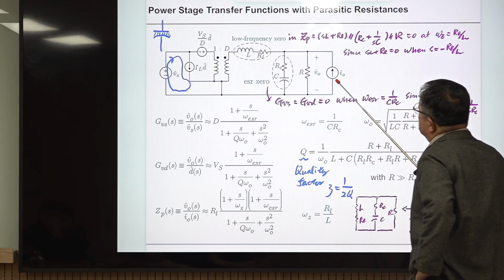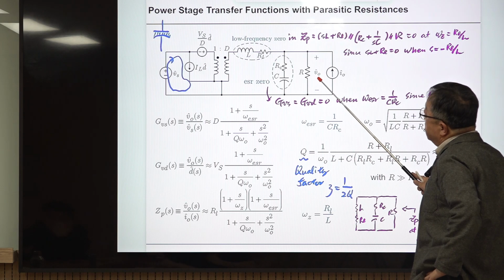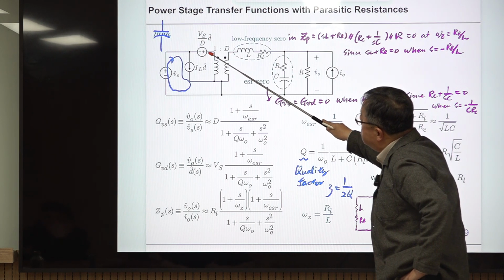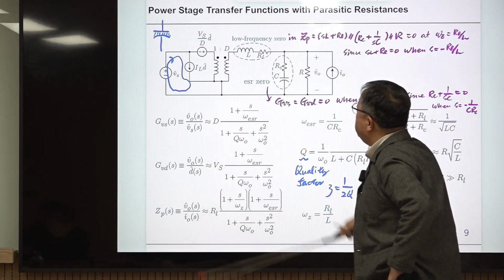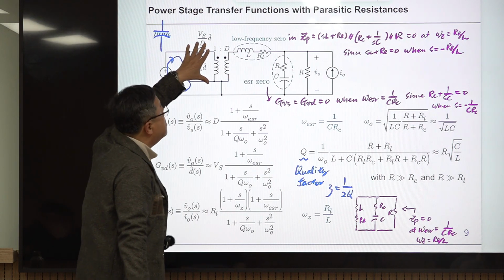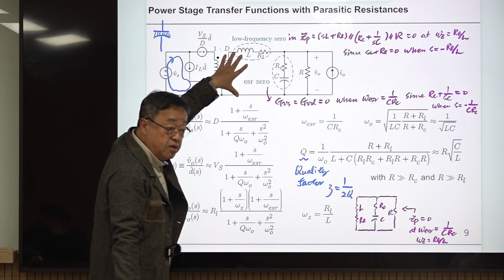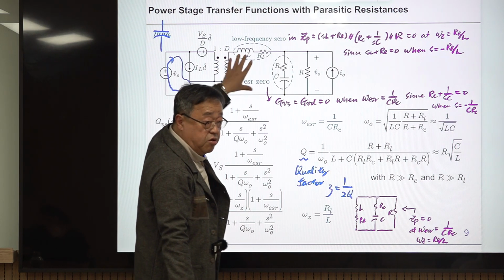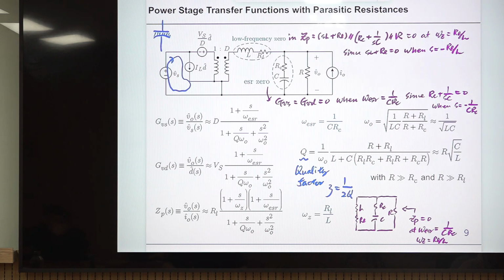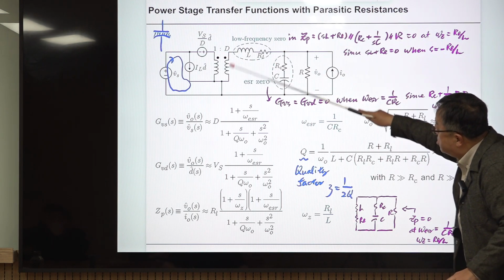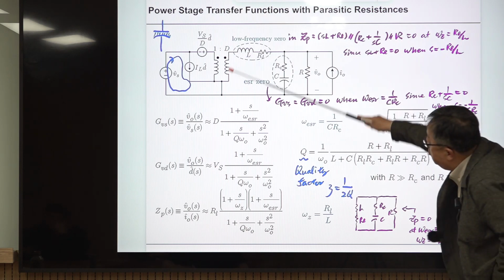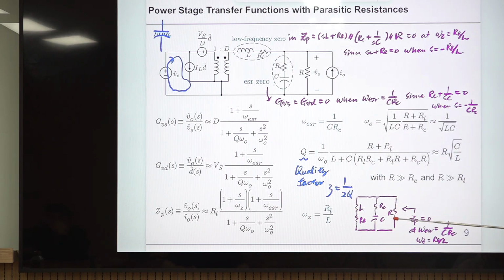And the last one is, this is input and this is output, okay? And this is shorted, and this is shorted. This is 0. Then this is shorted, right? In an ideal transformer, if the primary winding is shorted, then the secondary winding is shorted. Okay? That's the relationship, the circuit relationship of an ideal transformer that comes from the definition of an ideal transformer. So this is shorted. This is shorted. Okay? Then we have this. Everything is shorted. Then we have this in parallel with this.